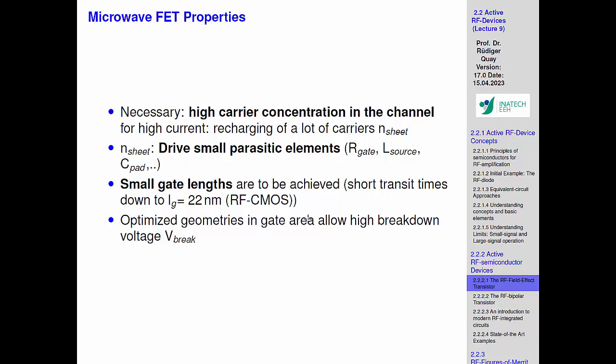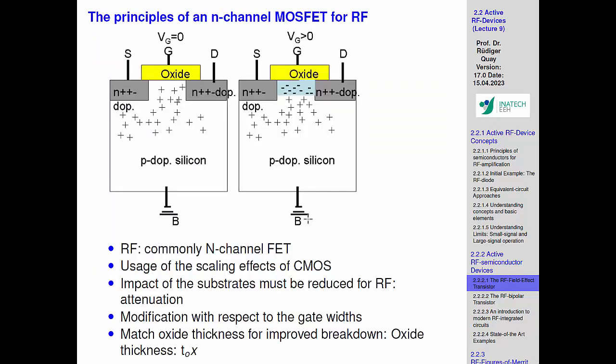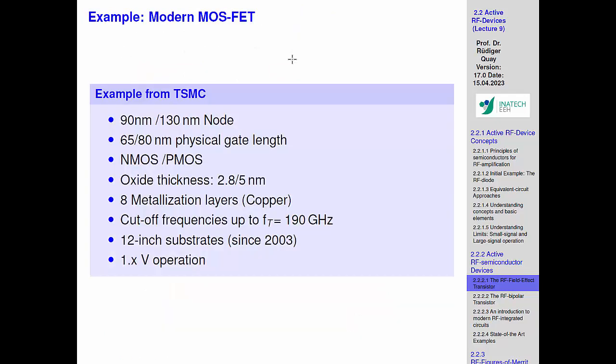There's all kinds of resistance, so I've taken out the main ones which we are always concerned about. The first thing is, if you have a MOSFET, but the metal on top over the MOSFET is very, very lossy, that in itself also constitutes a loss. So you have to charge and discharge this resistance. You don't want that. You want a very good material. Yeah? So that's typically what you want.